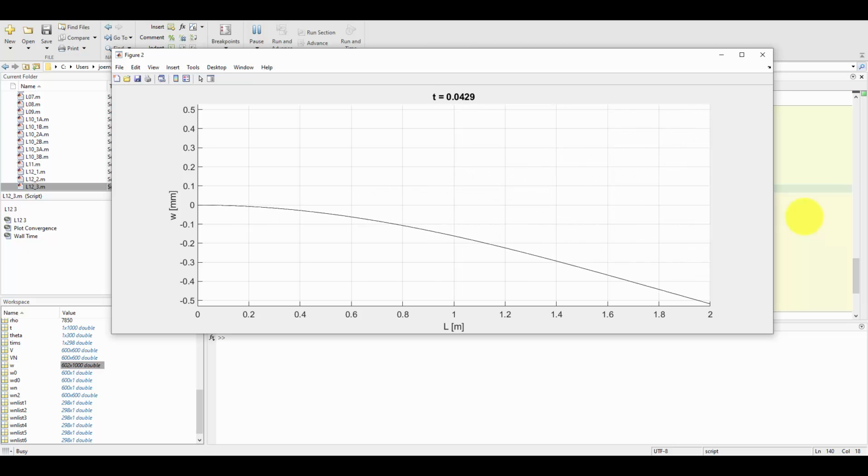So thinking back to in Unit 1 or Unit 2, when we had deformable beams like we have here, we said, well, we can use that static equation and treat it as though it's a 1 degree of freedom system. A 1 degree of freedom system has only one oscillation to it. It has only one frequency at which it would vibrate. But here, clearly it has more than one, and we see that because it has an infinite number of degrees of freedom.